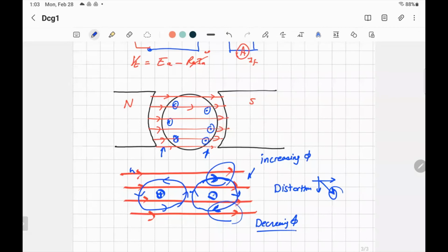If the flux is decreasing, the EMF will decrease. And if the flux is increasing, especially since we are operating close to the saturation region, as I said, the effect will be demagnetizing, decreasing the field, because you operate on the magnetization curve. So the increase will be very slight. You're not having control. The other one that's linear can obviously increase, but when you reach saturation, there's no more increasing. So you will find that the magnitude of the voltage you are expecting is not the same, it is less.